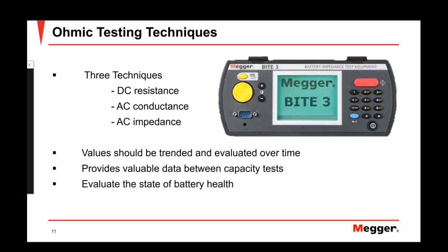Now, ohmic testing techniques, whenever we talk about that, we have to consider a couple things. So batteries have resistive, capacitive, and inductive characteristics. And that ohmic equivalent, we can measure that. Now, we can do it a couple of different ways.